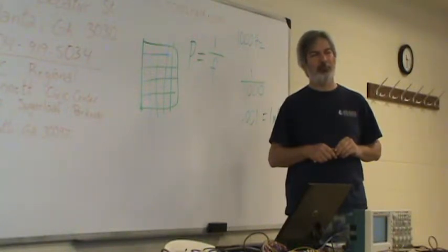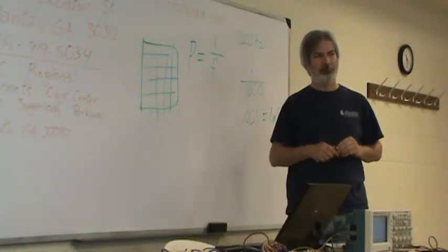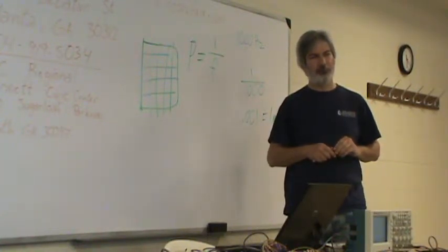But if you do it the other way around, start at the highest sweep rate, you're not going to get any aliasing there, and keep backing it down until you see a reasonable waveform. At least that's the way I do it.